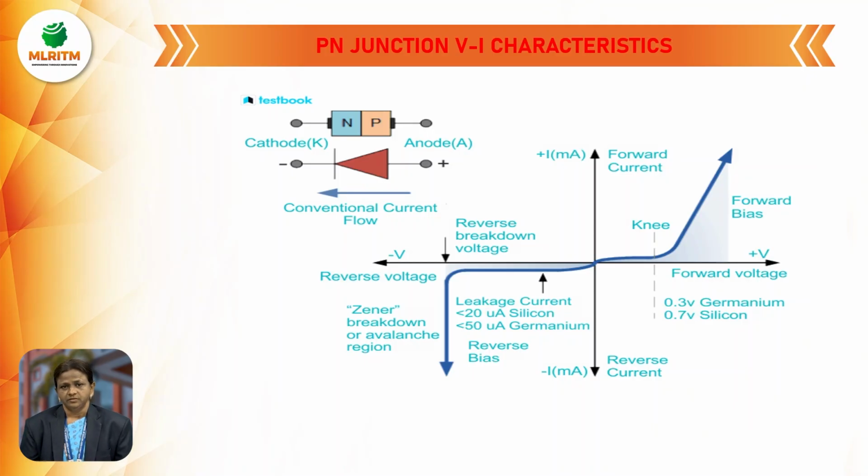So, the number of charge carriers or number of free electrons increases. This is known as carrier multiplication. So, whenever PN junction diode is in reverse bias, that breakdown is due to carrier multiplication. That breakdown is known as avalanche breakdown. Avalanche breakdown is due to carrier multiplication.